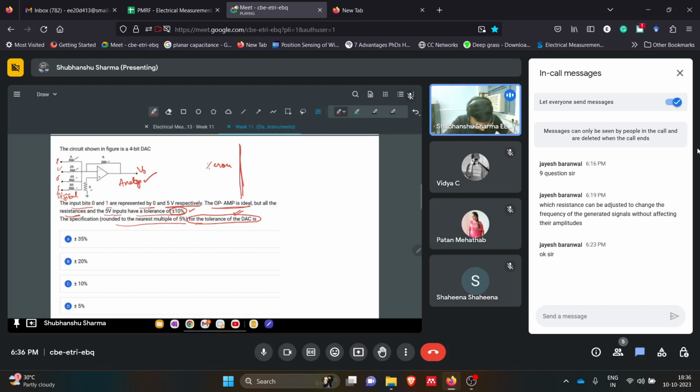Here, let's say this was 1111, something like that, and since this is an R and there will be no current flowing and there is no voltage source, there is no voltage drop here, so this is also 0 volts. So we can expect 0 here also, that is virtual short. Okay, so this is 0 volts.